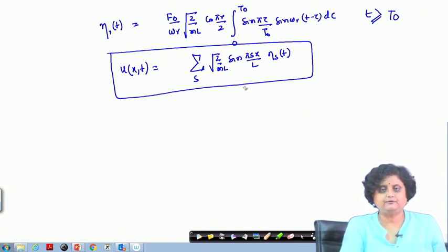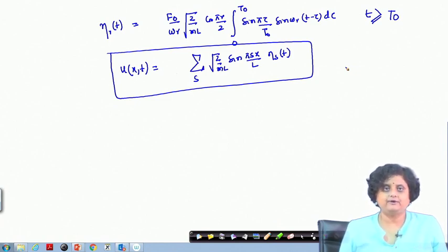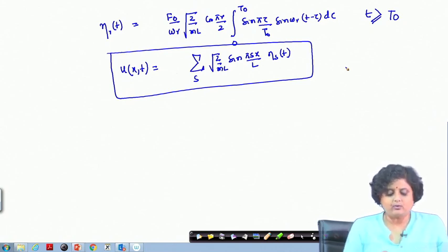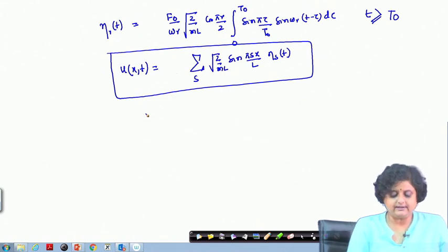It is important to know this vibration response, because under this vibration the missile is going to deform axially. So, strain and stress will be produced because of this deformation, and we need to know whether the missile will be capable of withstanding that stress due to vibration. Now, there was a rigid body mode which we did not consider.